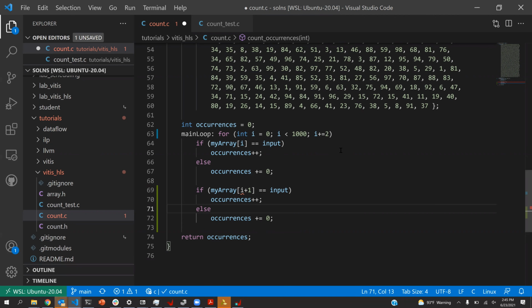Maybe. Depends how much your hardware can make it. So these are the problems of hardware design that we don't really get into in 220, but we talked about things being compute bound or memory bound. This is not a compute bound application. The computation is pretty boring. It is memory bound. We can run this thing as fast as we can get data out of memory. How fast can we get data out of memory if we put all of this in one memory?